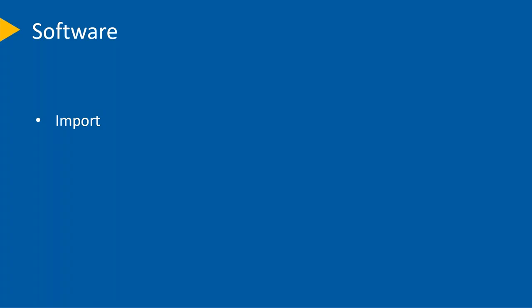Now, there's a couple of industry standard formats, such as E57 or LAS, that most softwares will bring in. But the one thing you might want to check is if you want to bring the scanner directly in to a specific software. So just check and make sure that the file formats that you want to use are supported with your software. Next step, the software will generally need to go through and do some processing on the data, either some cleanup or converting of file formats.